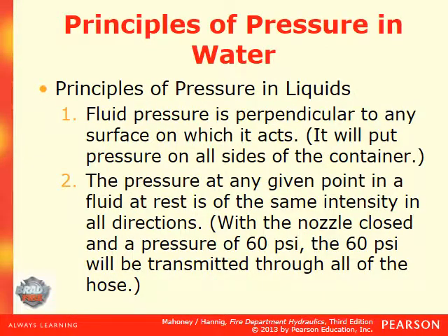So we have 6 principles of pressure that we deal with in hydraulics, and it will behoove you to remember these 6. 1. Fluid pressure is perpendicular to any surface on which it acts. Basically, it will put pressure on all sides of the container.